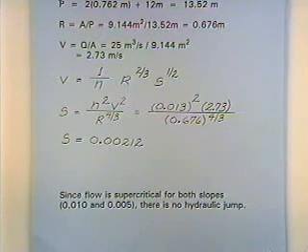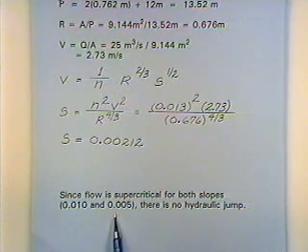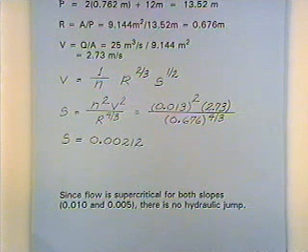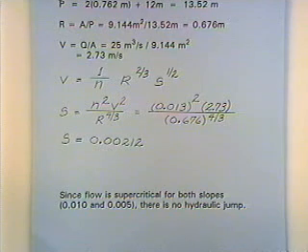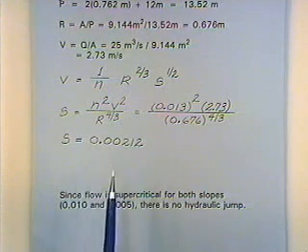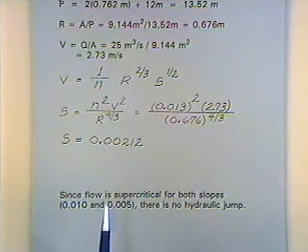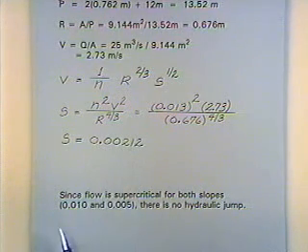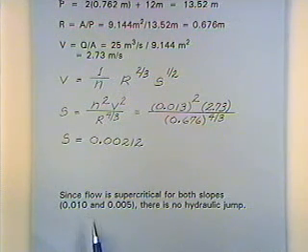And the significance of the 0.762 meters, that's critical flow depth. And so then I've got to think, what is it I actually have? My real actual slopes are 0.01 upstream, 0.005 downstream. And so I need to have supercritical flow upstream, subcritical flow downstream in order for the hydraulic jump to occur. And so to have supercritical flow, the slope has to be steeper than 0.00212, and 0.01 is steeper, so I do have supercritical flow upstream.